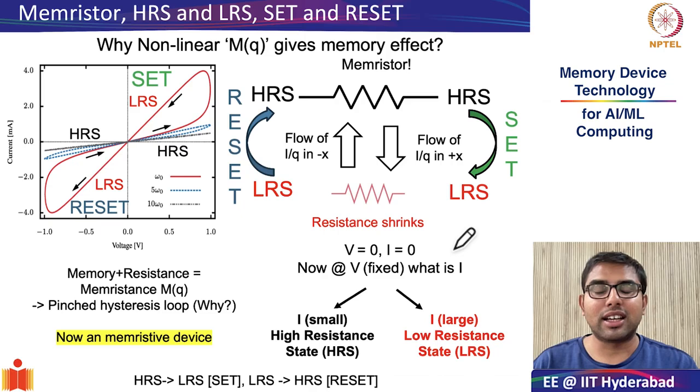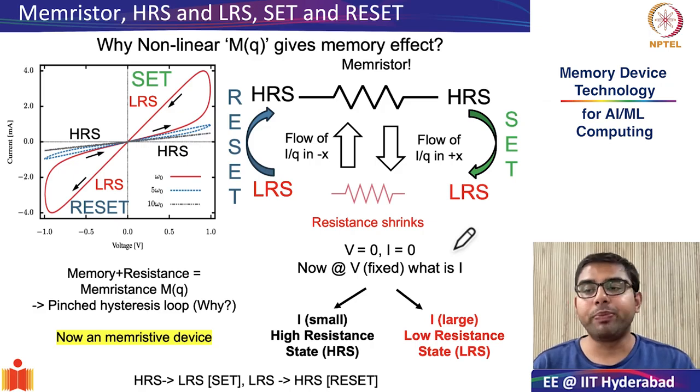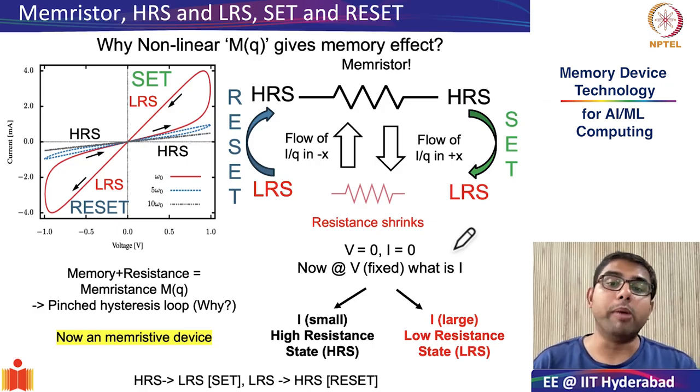So last class we began with a very interesting topic. We began the second part of our course. Let us try to recall what we had studied the last time around. We saw how by having passive two-terminal elements as non-volatile storage devices, we can effectively bridge the gap between DRAM main memory and NAND flash, which is the main storage. And these passive two-terminal elements can be known as storage class memory or even ENVMs, electronic non-volatile memories.